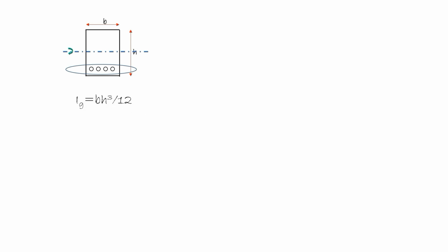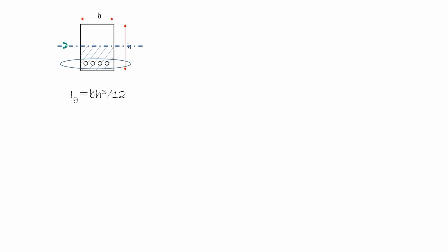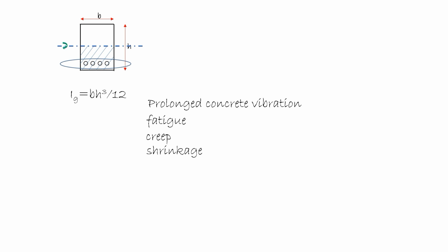However, concrete is very weak in resisting tensile stresses. In any structure with a concrete beam, for instance, cracks in the concrete beam will be visible due to many reasons, like prolonged vibration of the structure due to earthquake, fatigue, creep, and shrinkage experienced by the materials as time goes on.